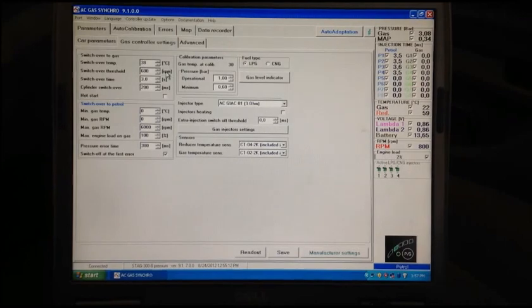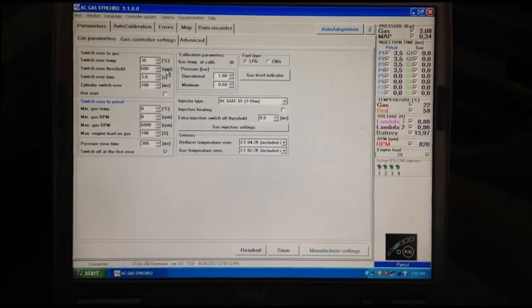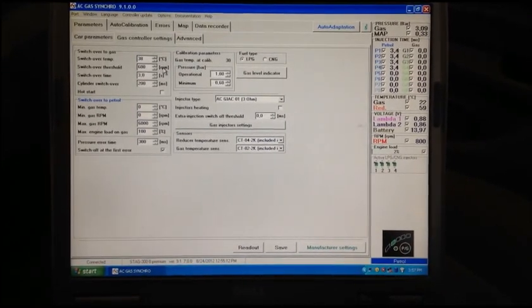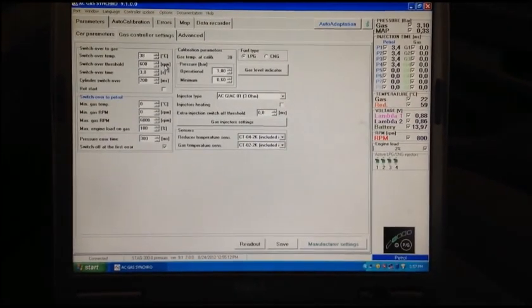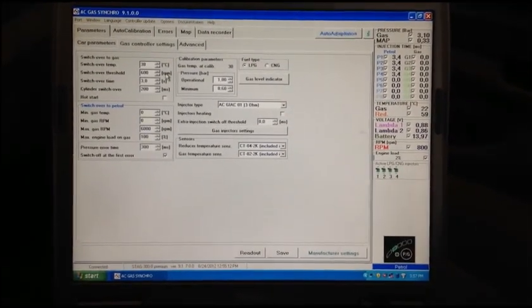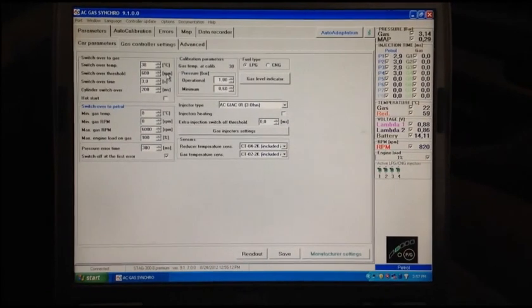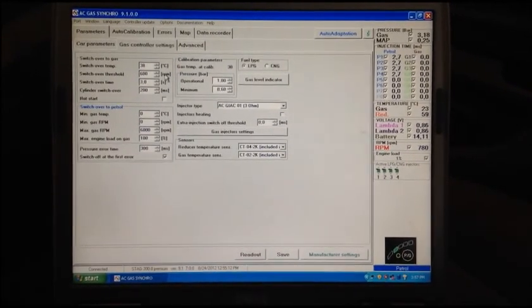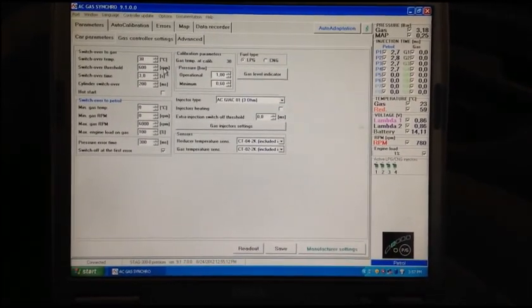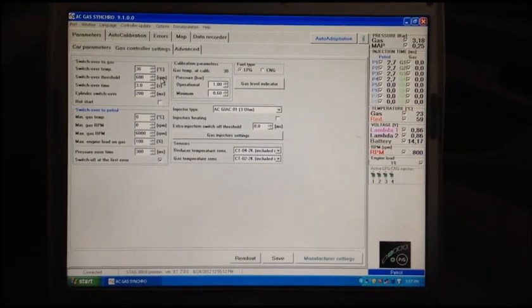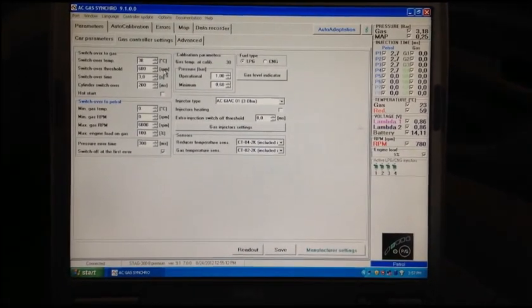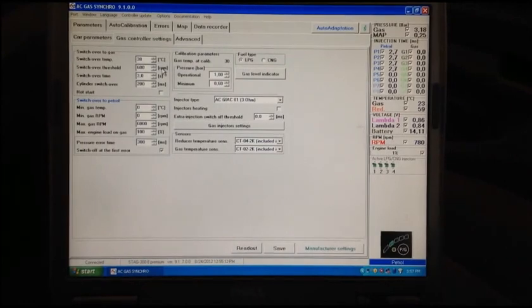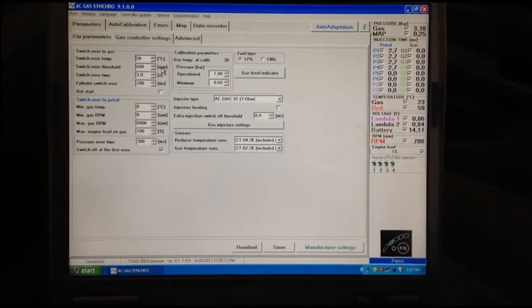and that way you have to be underway or actually rev the engine up to a predetermined RPM for it to kick in. And once it's under load or you're at a higher RPM, the engagement's going to be much, much smoother. But typically if you got your hose lengths right, your nozzles are in the right spot, everything's set up properly, and you got it tuned real nice, you can have it kick over at an idle and you'll just barely feel it kick in.